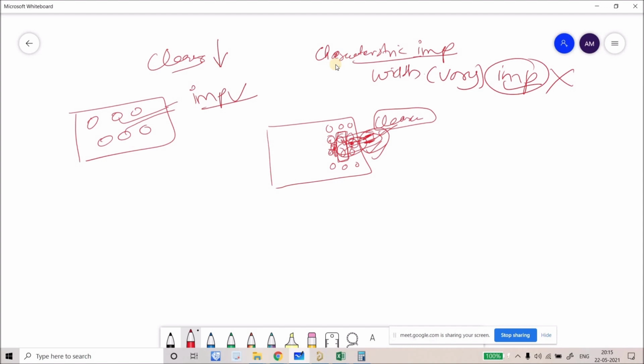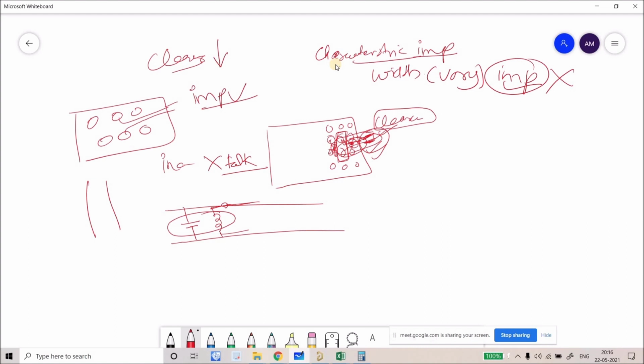How does coupling, interference or crosstalk work? Anybody want to answer that? Okay, it is electromagnetic coupling, right? Whenever two tracks are running parallel, I already told you, it has capacitive coupling and mutual inductance, because we have inductance running here. Because of these two, a small amount of current will be induced on another track, or you can say the silent one, right?